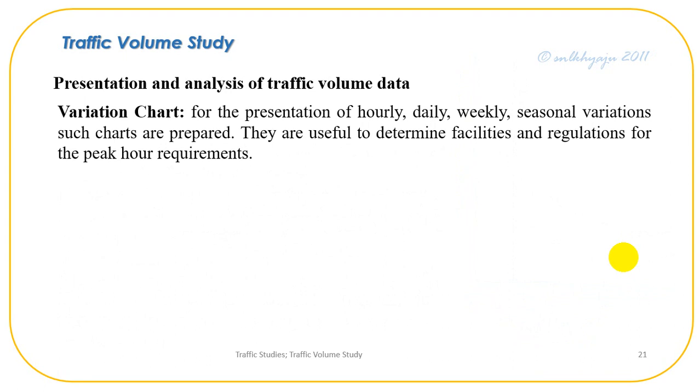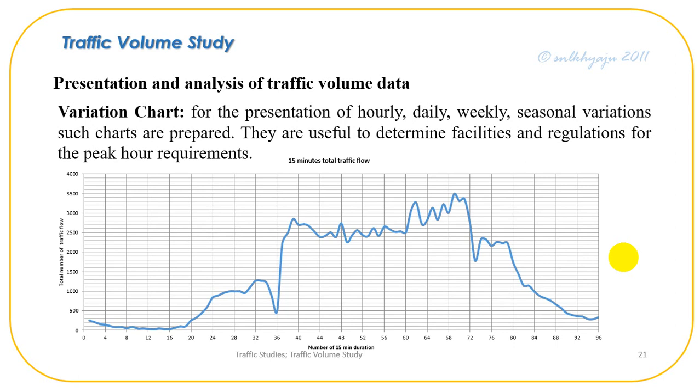Now, variation charts. For the presentation of hourly, daily, weekly, seasonal variation, such charts are prepared. They are useful to determine facilities and regulations for the peak hour requirement. And this is the chart showing the 15-hour total traffic variation in a day.